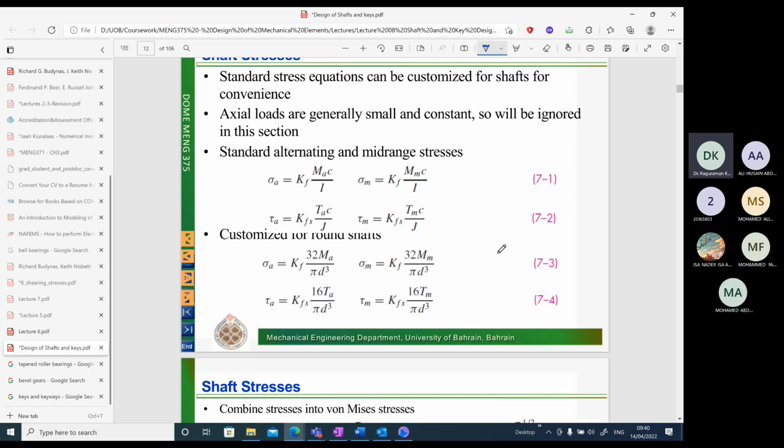Okay, so what are the equations? Now we may have a static load or a dynamic load here. So we need to consider both the cases, and in the fatigue equations we look for both static yielding and also fatigue failure case. So in this case we need to find, as usual, the amplitude of stress and the mean stress values.